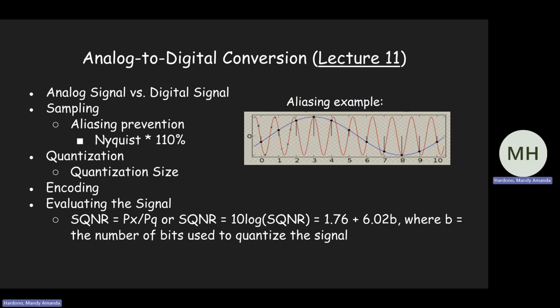The next stair step up is going to be 1, the next stair step up is 2, etc. For the encoding, you could do 0, 0, 0 for 3-bit resolution to represent 0. Then for 1, you do 0, 0, 1. Then for 2, you do 0, 1, 0, just those numbers in binary using a 3-bit representation. So that's the encoding part.